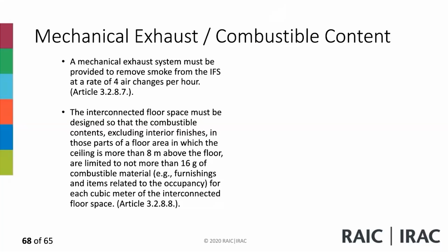In some of the areas where we're looking at a lot of fuel contents, you have to address it, especially where you do expositions with multiple floors opened onto them. The interconnected floor space must be designed so that combustible content, excluding interior finishes, in those parts of the floor area in which the ceiling is more than 8 meters above the floor, is limited to not more than 16 grams of combustible material for each cubic meter of the interconnected floor space.